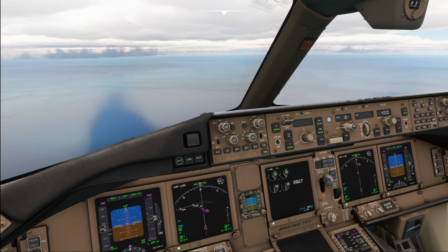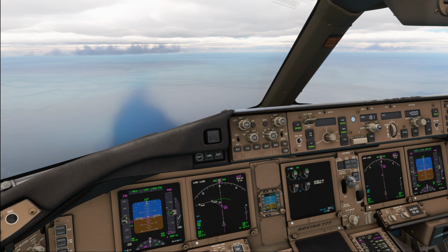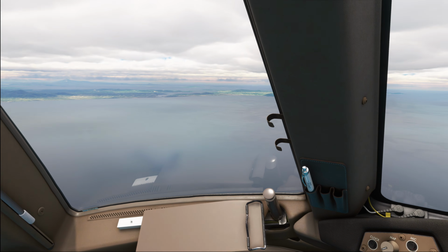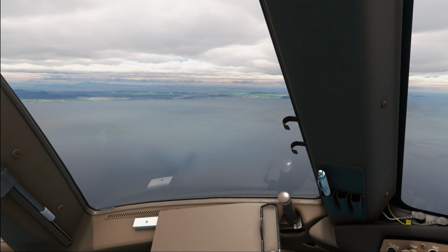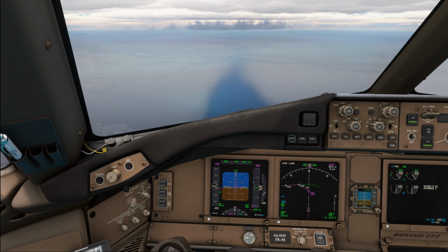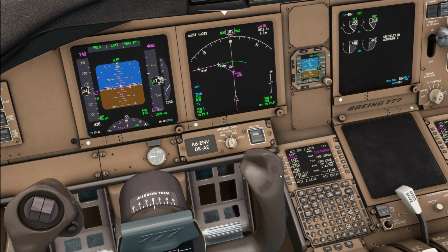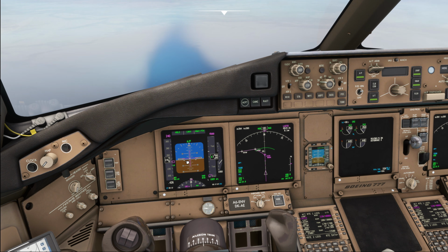And once we are on the final approach, visual with the runway, we can disengage the autopilot, make sure to maintain the glide path for the manual landing. As soon as the visual approach aids, that's normally the PAPI, are in sight, we are going to refer primarily to the PAPI. But if you actually have a runway waypoint available in your FMC, which we do not have today, but if you have a Romeo Whiskey whatever point, Romeo Whiskey 09 for a runway 09, then the flight director may be used all the way down to the final approach for as long as it gives good guidance.